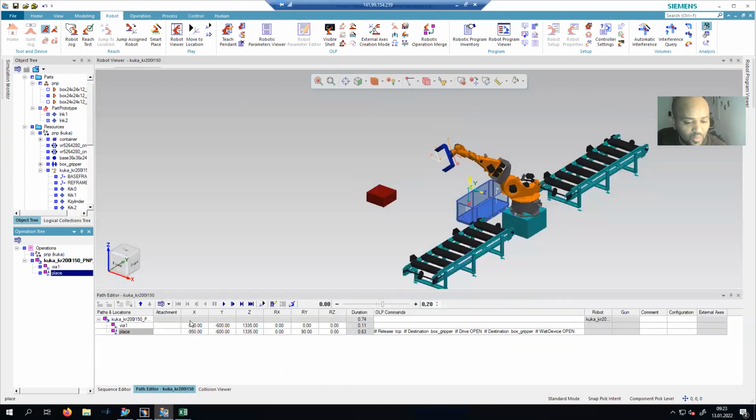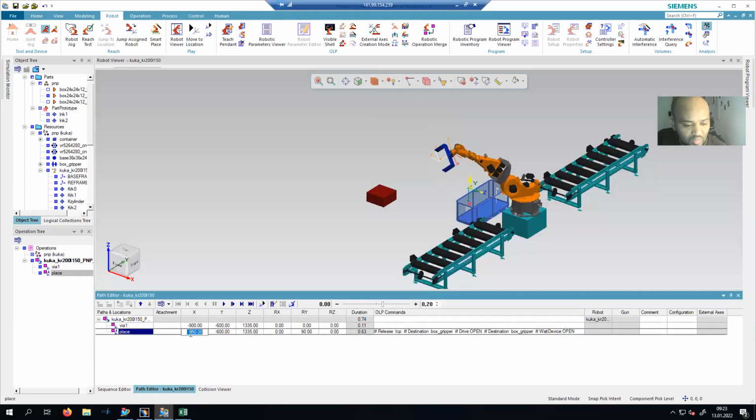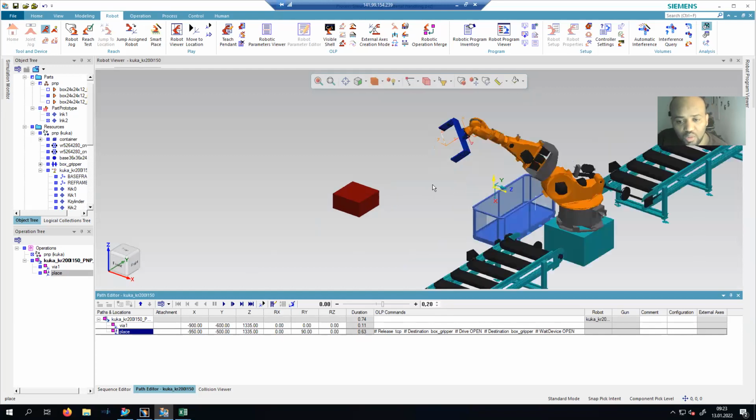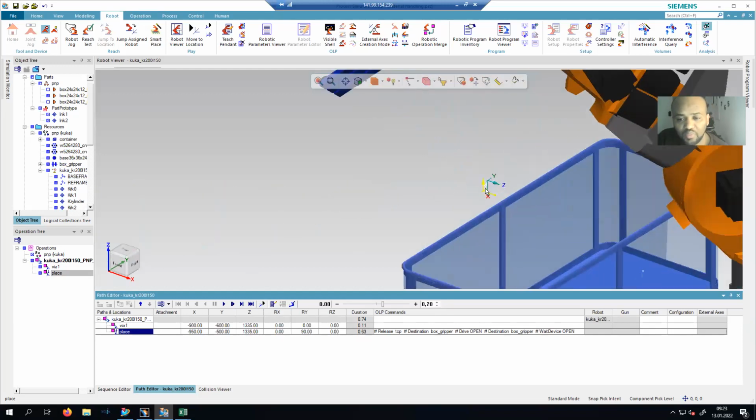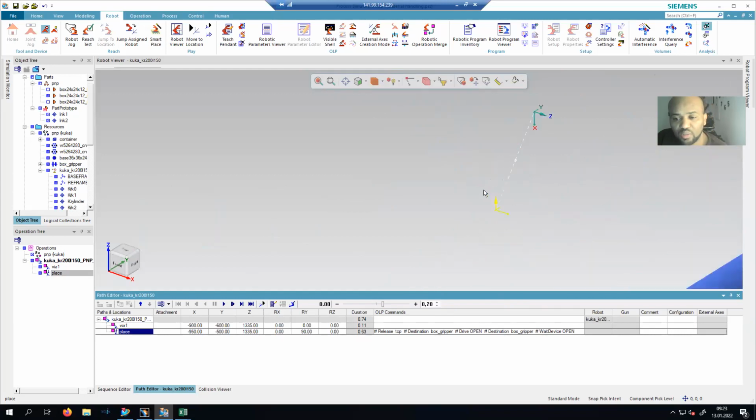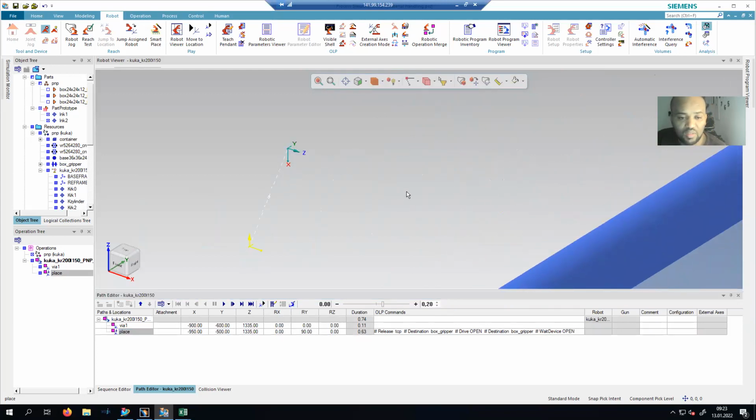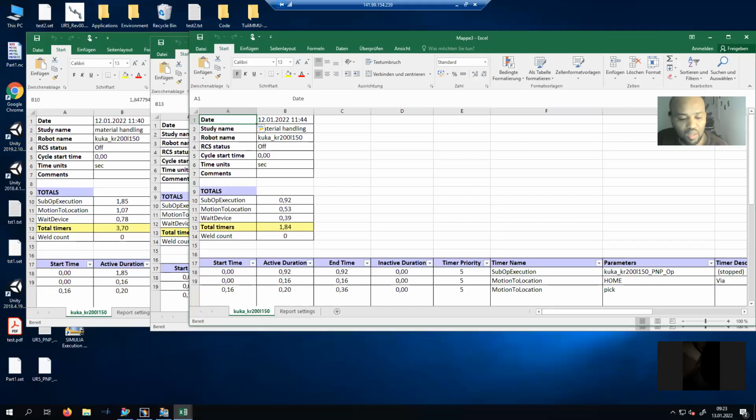So you could transform. You could easily transform from this point to this point. So with the transformation matrix, you could move from this to this point because of the homogeneous transformation matrix. And this homogeneous transformation matrix is represented by the Denavit-Hartenberg convention. That is the most frequently used modeling approach.